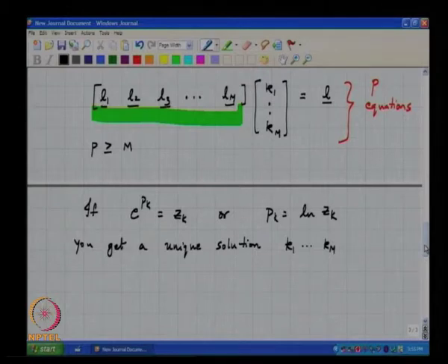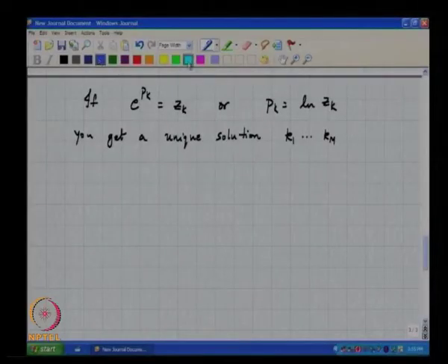If the pulse is messy, not because you want to deliberately make it messy, but because of the way the DAC is designed, let us say the pulse is not really a rectangle. Ideally this is the NRZ pulse that you want. In practice, no edge can be perfectly sharp. So, a practical NRZ DAC pulse will probably look like this.